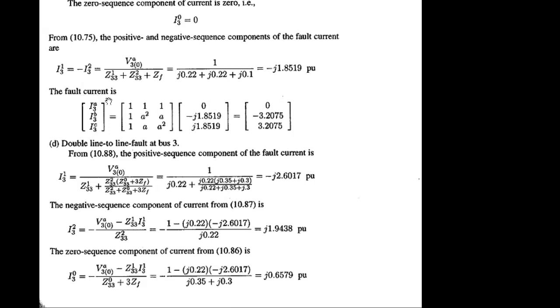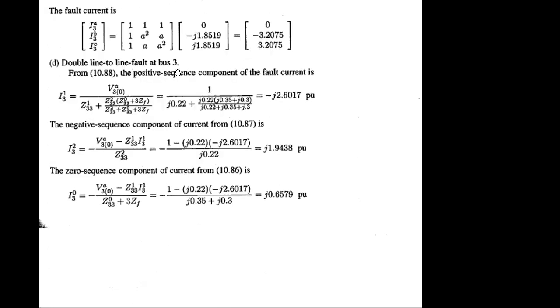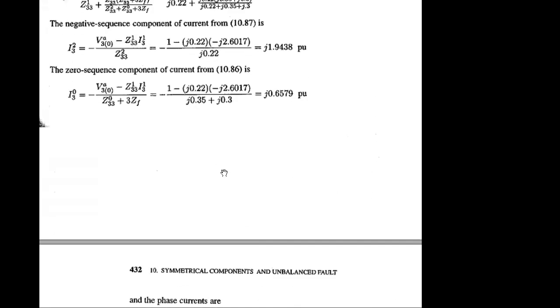For current calculation, the first step is to determine fault current for all the scenarios. When you complete this fault current, you have this part as 0, 1, 2, and this side is ABC in terms of I3. So after completion, you can get the total fault current for double line, which is I3B plus I3C. This part is for double line to ground fault. For other faults, you can use only IA information.